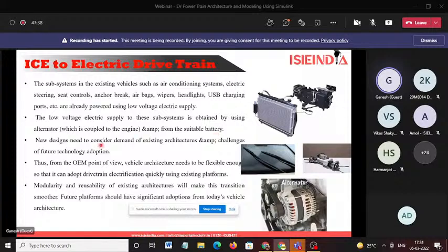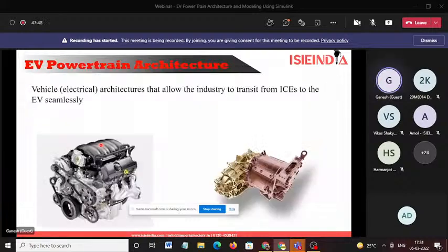When we are using the motor, we don't have any alternator. Basically, how your alternator works is that it is attached to the pulley of your engine, and based on that the alternator generates the power. But coming to the electric vehicle, we don't have any such pulley and we will not use any alternator. The only power source here is the energy from the battery. If you want any energy from the battery, we need to take the power source from the battery using DC converters.